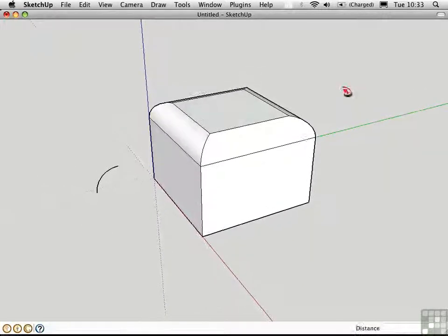We can take it to the next level by creating an eighth of a sphere right here in this area. And we can do that using this arc. We'll use the Follow Me tool to sweep out an eighth of a sphere from this arc. To do so, we need to start with a face, so we need to fill in the missing lines. Use the Line tool and draw a line over in the green direction. Lock your inference by holding down the Shift key, and then draw in 2 segments to complete this little pie shape. Then draw a circle underneath.